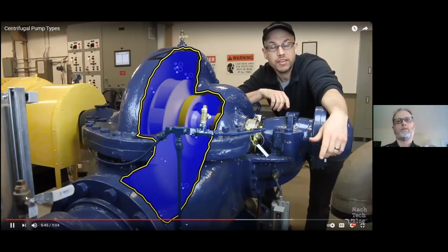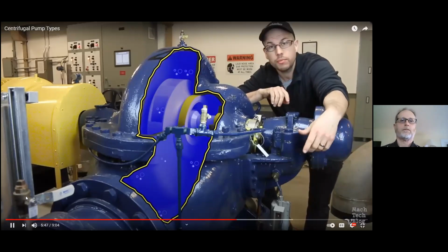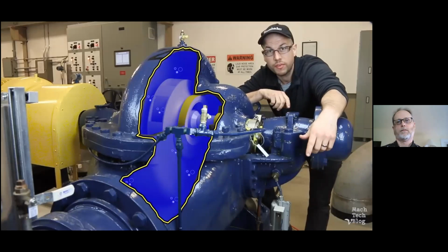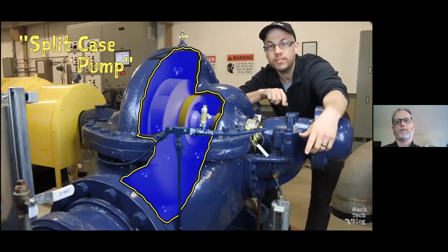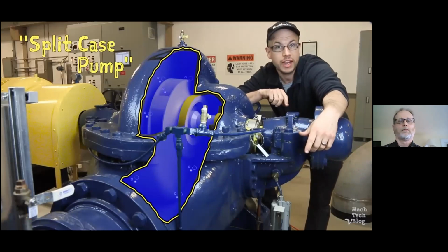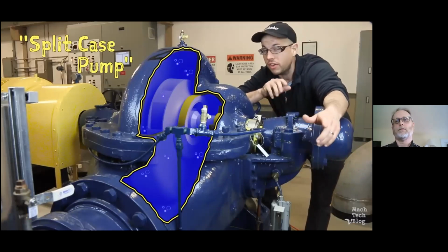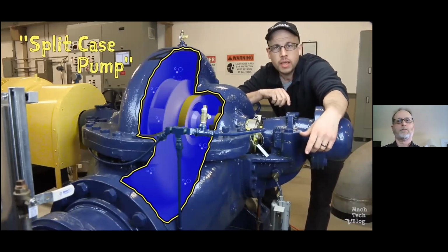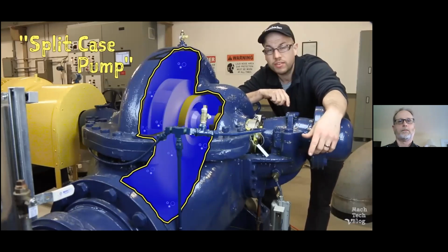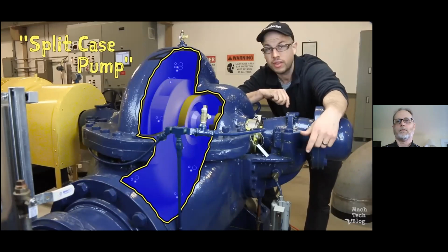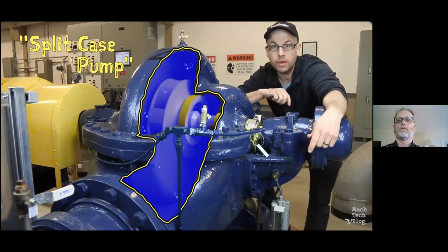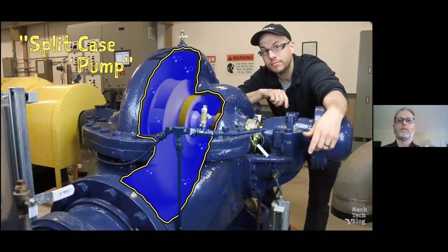This axially split design is why pumps with impellers between bearings are more commonly referred to as split case pumps. Now, those are all pretty convincing reasons to go run out and get yourself a split case pump right now, but of course there has to be a disadvantage. Because the manufacturing processes and the sealing requirements for split case pumps are much more elaborate than for end suction pumps, they're also naturally more expensive.